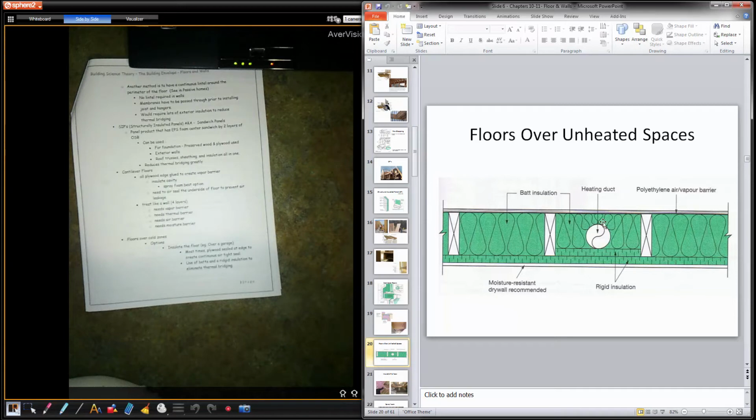So you can spray foam underneath here first and then kind of work your way out with the spray foam. A lot better results, more cost, but better efficiency. So if you have a tight budget, maybe just spray foam these areas, right where the ductwork is, and then the rest fill with batt insulation, and then follow with continuous insulation, and then air sealing.